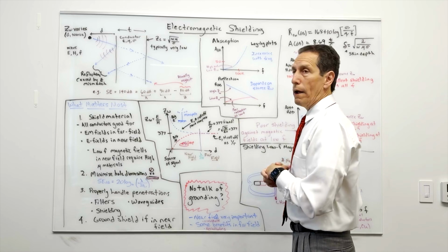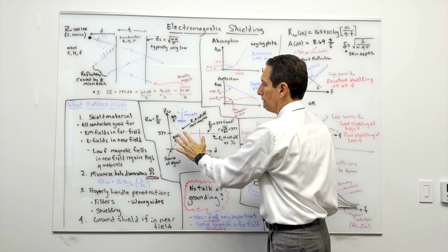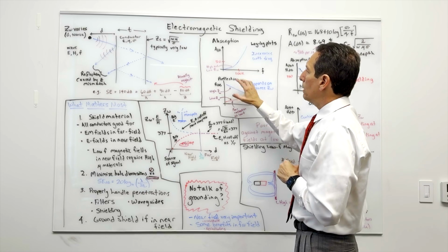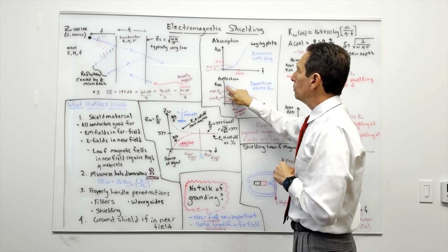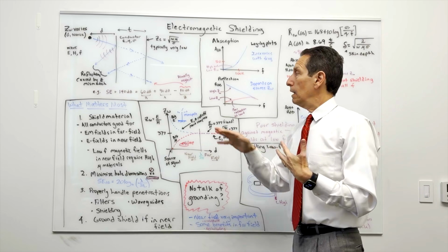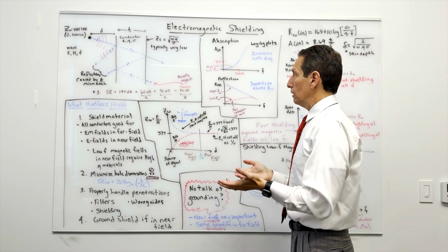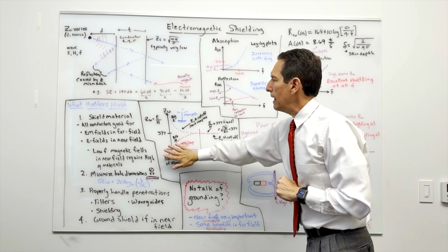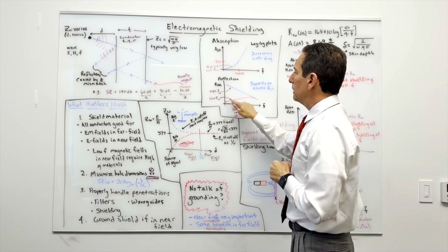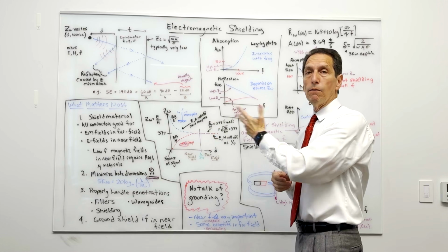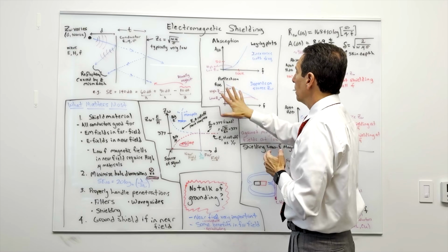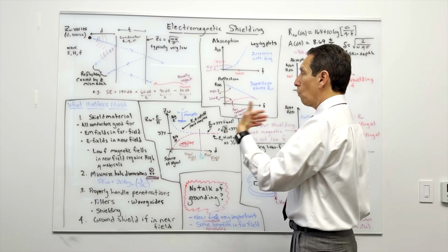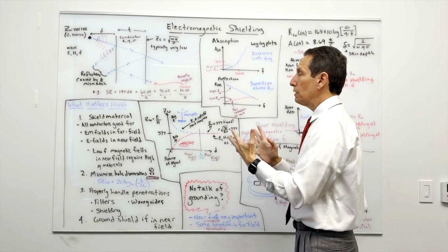And if you have a low wave impedance, so maybe you're on this red curve here, down here, you've got very low wave impedance, you're going to follow this curve here, okay? So what does it tell me? It tells me that you get really good reflection from this electric field dominated emission. You get really high values of reflection, it gets reflected off really easily. But this magnetically dominated emission really doesn't get much reflection. It manages to not get reflected off the metal. So that's how it's showing you the reflection is really dependent on the type of the source, the wave impedance, which is dependent on the source and the distance.